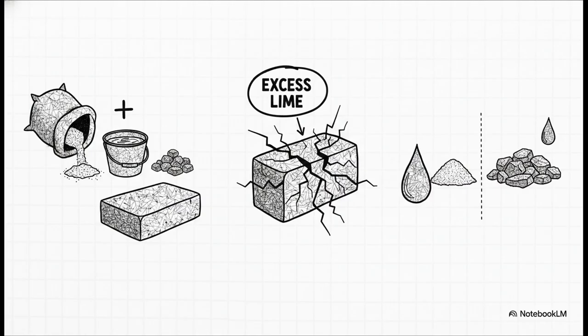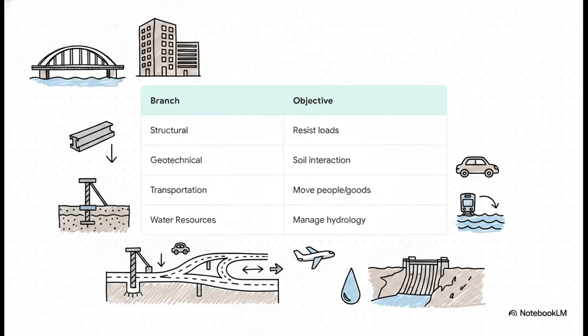Lime provides strength, for sure, but excess lime will make your cement completely unsound. Finally, don't misjudge your aggregates. Fine aggregates, like sand, actually require more water than coarse gravel simply because they possess a much higher total surface area. For your daily study reference, I highly recommend you take a quick screenshot of this summary table right now. It cleanly aligns each major engineering branch with its core objective, from structural load resistance all the way to managing hydrology and water resources. Definitely keep this handy as you read through your textbook this week.